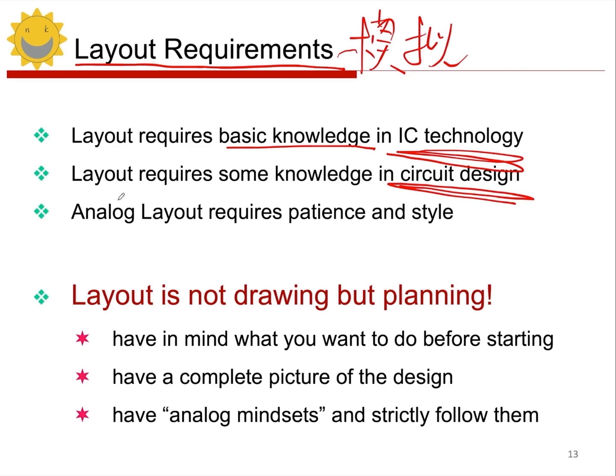You need patience because the level of hand drawing is high for analog circuits. You must consider factors like matching and parasitics, which are time-consuming. Style refers to personal habits, like preferred matching methods or component isolation.